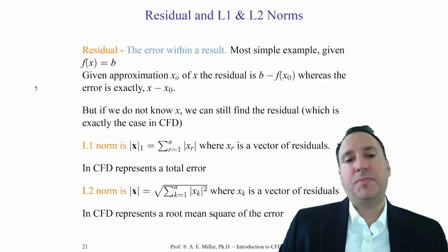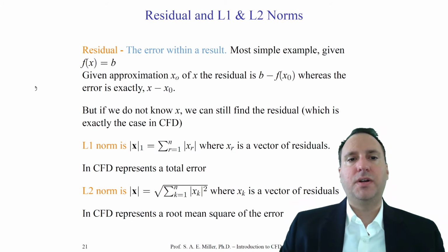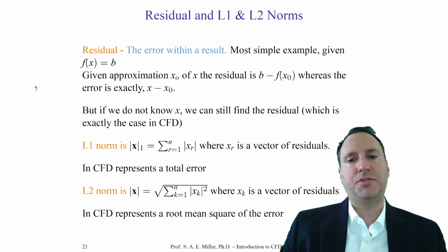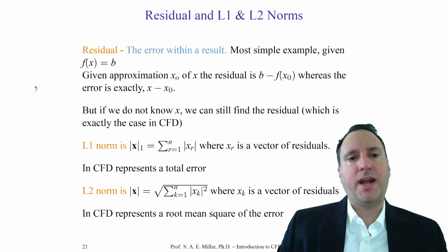If we do not know a particular value of x, then we can still find the residual, which is exactly what we do in CFD. The exact value of x, perhaps, is something that we would do with x naught in an analytical solution. This is not particularly done in CFD because, of course, we don't know the analytical solution. There's two types of ways to measure a residual.